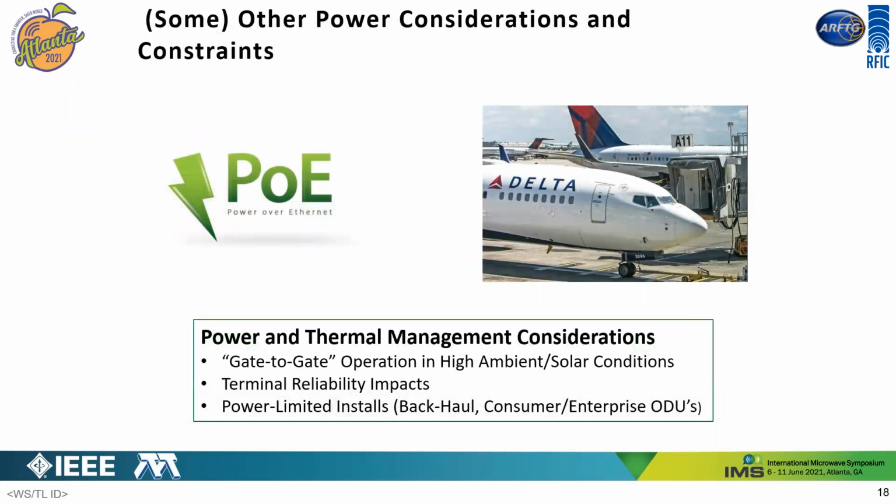In terms of practical operational considerations, and specifically in the case of small consumer or enterprise SATCOM terminals, it can be highly advantageous to limit total prime power requirements, such that they're compatible with power over Ethernet, thereby enabling a simple one cable interconnect that can be employed in connecting the outdoor unit, or ODU, to the indoor unit, IDU, and the modem.